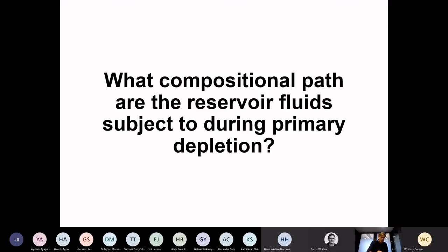And here, I think at this point, it can be nice to mention that in conventional reservoirs, the producing GOR, so that's the Rp, is a strong function of the average reservoir pressure. And in unconventional reservoirs, for the Wintershall guys that will be in Vaca Muerta, the same with Equinor in Vaca Muerta and Bakken, it is a function of the flowing bottom hole pressure.